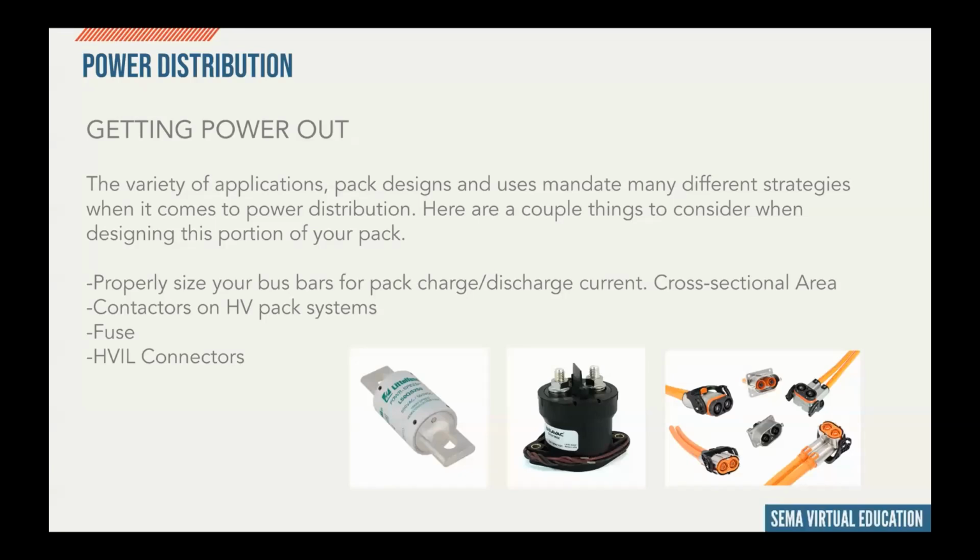There should also be a high voltage fuse, rated for pack voltage and amps, inside the battery pack, so that if there is any problem externally from the pack, the fuse can blow and protect the pack, its contents, and externally the vehicle and its users.